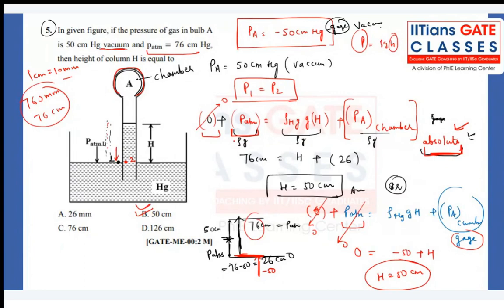So I told you about pressure. Suppose the pressure at Agra or pressure at Bangalore at a particular location, right? Suppose they have given the value as 26 kilopascal. Now tell me, at a particular location, whatever the absolute pressure, the total pressure they have given is 26 kilopascal. You only tell me, the atmospheric pressure in our Bangalore is 100 kilopascal, and you are measuring only 26 kilopascal. Now tell me, is there a vacuum or positive gauge pressure? You only tell me, guys.